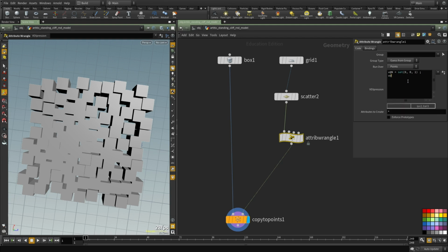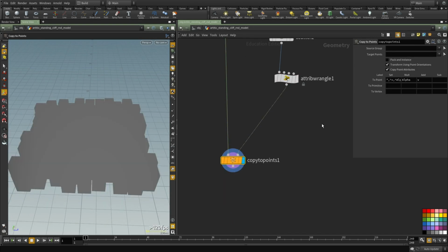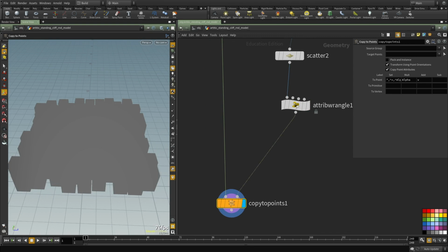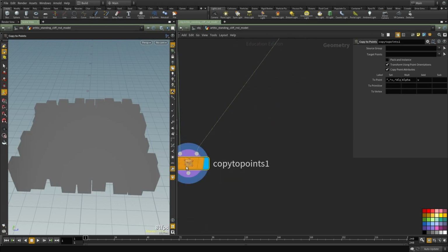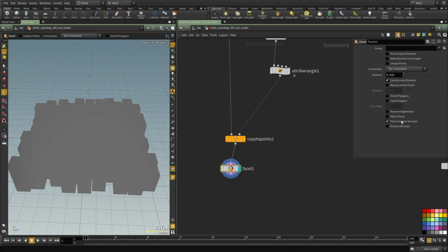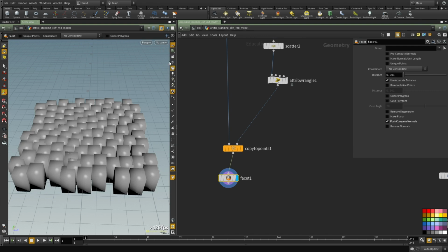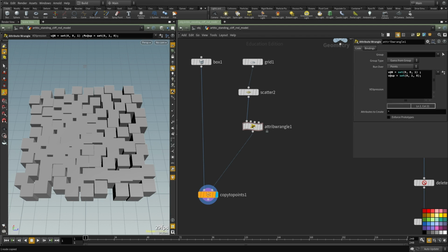and then we need an up vector. So up is equal to set, and the up vector is going to be set to positive y. Cool. So now once we have that, let me check something super quick. Cool. Once we have that, we are able to do a variety of things and rotate this geometry. Let me put down a facet SOP. Let's change this to flat shaded. Cool. Don't need that. And the first thing I want to change is the scale.